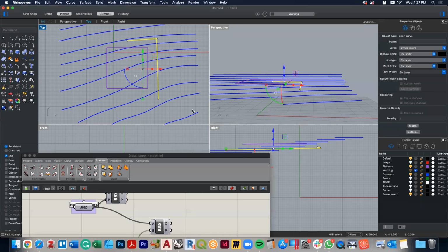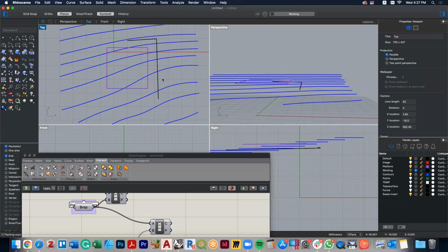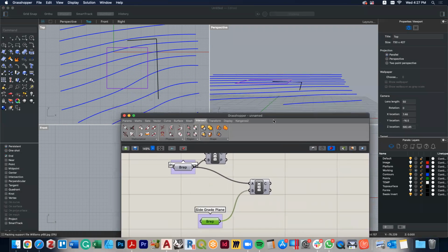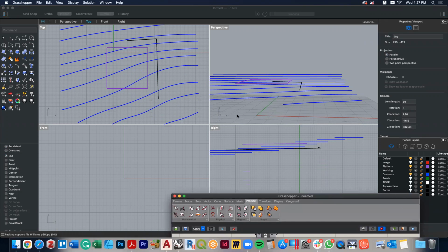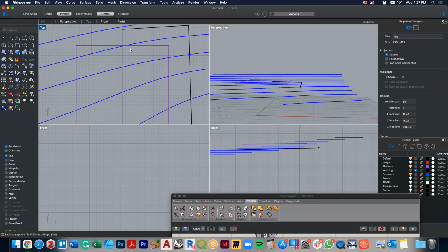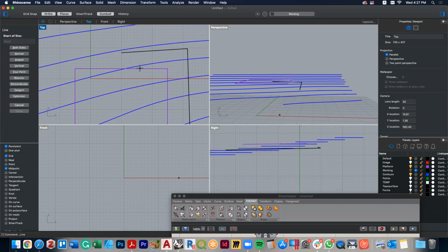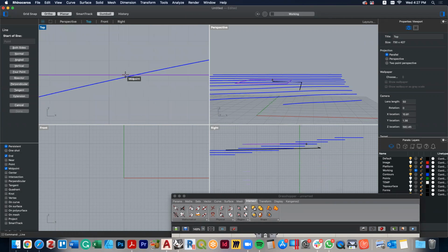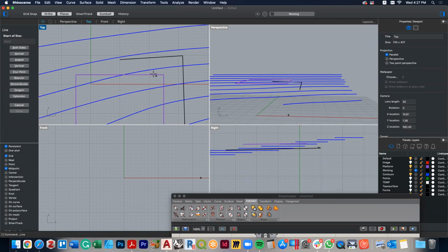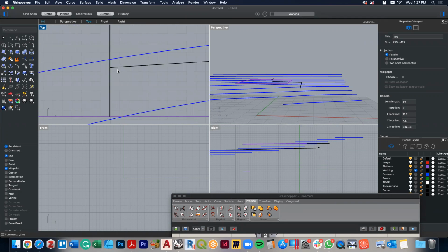And so at this point, what I'm now going to do is start by mirroring it. So I've put Grasshopper away for a little bit, even though mirroring is really easy. And so the first thing I'm going to do is I'm actually going to draw a line. I'm going to turn midpoint on again. And I'm also going to turn ortho on again. And I'm going to draw a line where I want to actually snap to the midpoint of the platform. And then I move up and it should be, and it is, there it is.